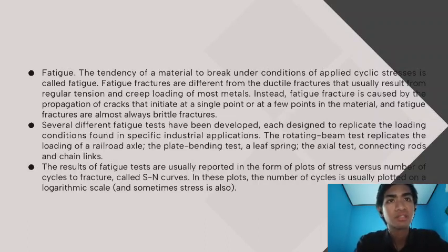The fatigue stress reduction factor, or fatigue notch factor, can be determined by dividing the fatigue strength of a smooth specimen by the fatigue strength of a notched specimen.